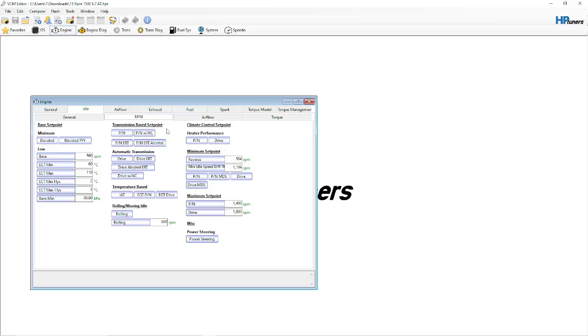The ethanol content, the barometric pressure of the altitude is different. The weather is different. The humidity is different. The wear on the seals on the intake manifold or other parts of the car is different. The wastegate may have dirt or dust that's causing it to get stuck within the diaphragm. There are so many factors. There's not one shoe fits all.